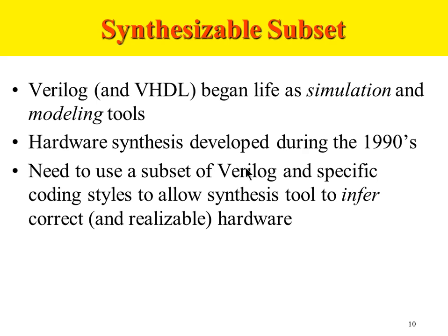Synthesis tools will take Verilog as an input and infer, meaning they try to understand what the Verilog code means and what hardware netlist has to be generated for it. That process is called inferring. So it will infer the correct hardware out of the Verilog description given to it. That is the role of the synthesis tool. You also have to understand to a certain extent how the synthesis tool works. There are certain coding styles that, if you follow them correctly, let the synthesis tool know what hardware the Verilog is meant to implement.